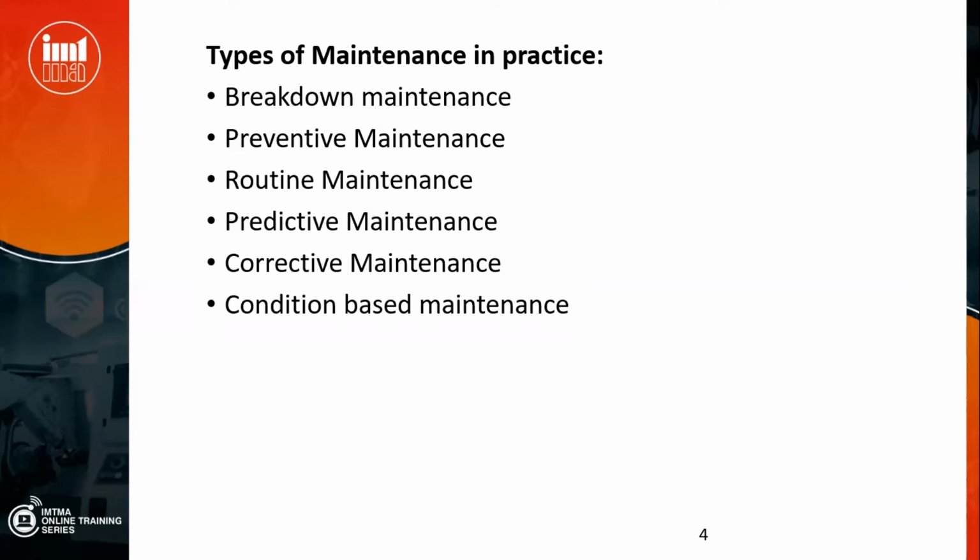We are monitoring the conditions by way of vibration, noise, or wear out particles, or suspended particles in the lubrication oil. In various methods of that itself is a big condition-based maintenance. We are analyzing them. If it is within the prescribed limits, we are not taking any action. This will indicate which parts are wearing out in a machine, whether the bearing parts are wearing out, whether oil contains certain suspended particles. So analyzing those things, we will be doing that.